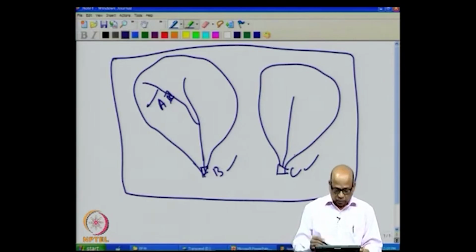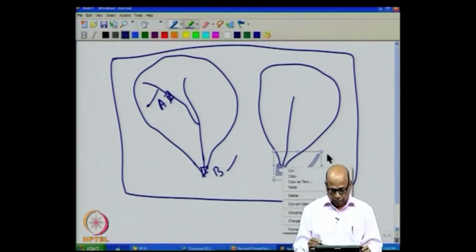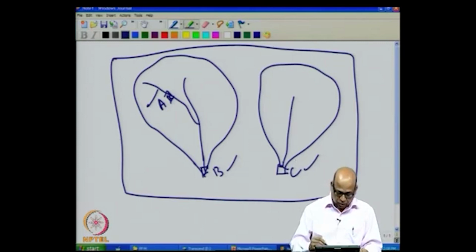In our single site models, what would we have done? We would have taken the flow records at this particular site C and then used a single site model such as, for example, the Thomas Fiering model to generate the flows, which would have preserved the mean, the variance as well as the lag 1 correlation of the flows at this site.